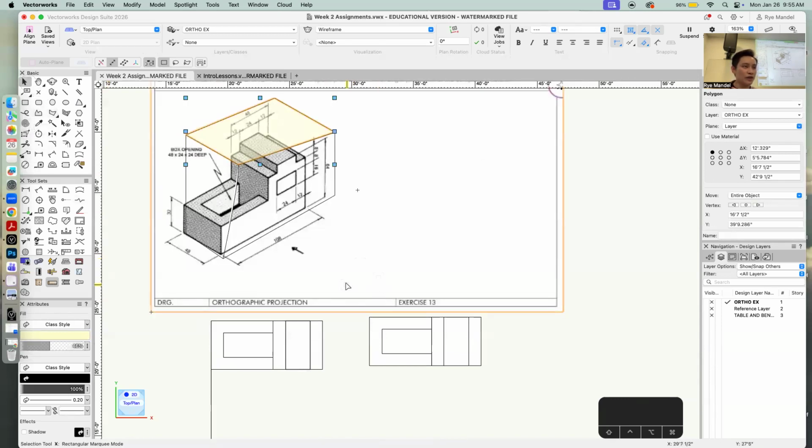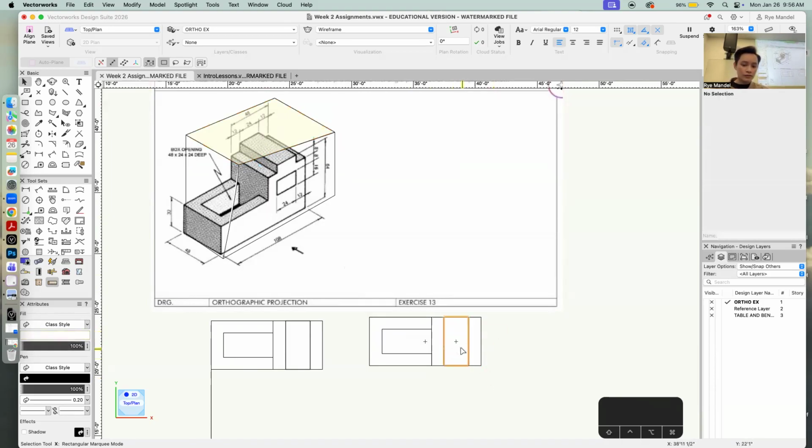If you have a ground plan, for a plan view, usually you want to cut it at 3 feet. We'll get to this a little bit later. But since this is such a small object, we're just going to do a top view, which is directly looking at it from above down and not cutting it at all. So this is how I got to here. Is everybody caught up to where this is again?